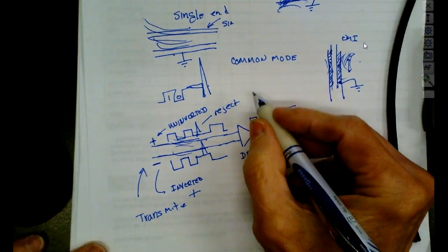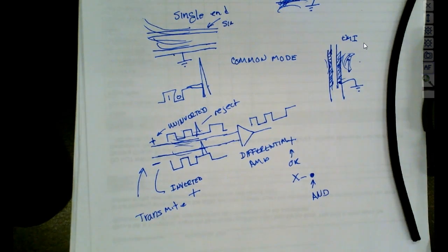So USB is differential, universal serial bus is differential, serial ATA is differential, which is the way we interface mass storage devices, hard drives and stuff to computers now. Ethernet is twisted pair. So eventually, even with Wi-Fi or wireless, eventually you've got to go back to hardwired stuff. You've got to wire stuff. So I can't amplify without using wires. So I might receive it, bring it in using differential, and re-amplify it.